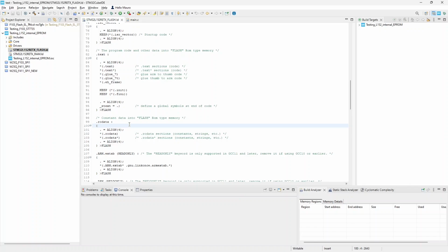Other than RAM and flash, some STM32s, like the F7 and H7, have an L1 cache. That, again in few words, is a small portion of an ultra-fast RAM memory, allowing to improve performance, accessing microcontroller programs and data.